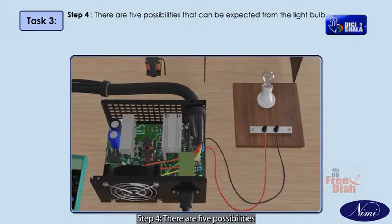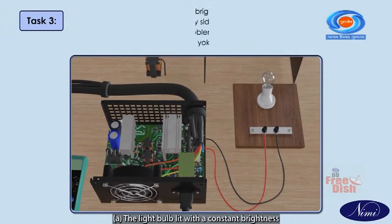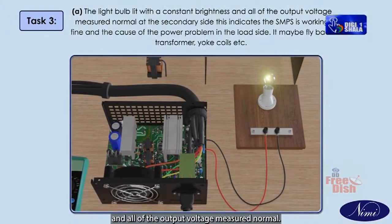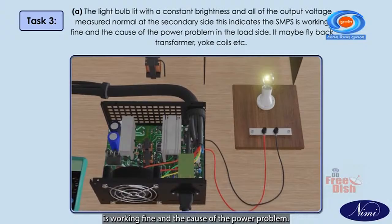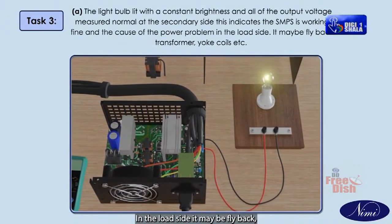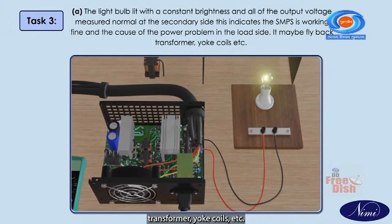Step 4. There are 5 possibilities that can be expected from the light bulb. The light bulb lit with a constant brightness and all of the output voltages measured normal at the secondary side. This indicates the SMPS is working fine and the cause of the power problem is in the load side. It may be the flyback transformer, yoke coils, etc.